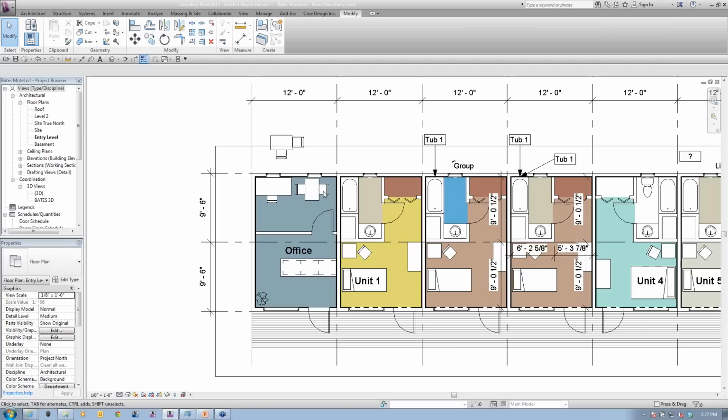Another alternative I'll throw in there is that I've seen a lot of people use Storefront, where there are actually window types they might be able to use. So if I had a really modern storefront window in here, I actually have a window type that I can use instead that would function a lot easier, and then you're just going in and controlling that family to get things done.